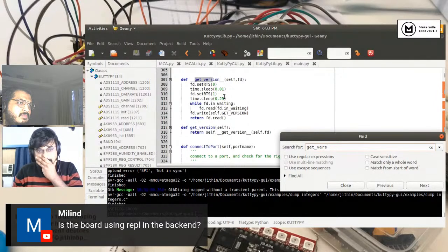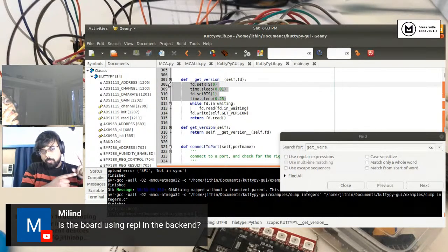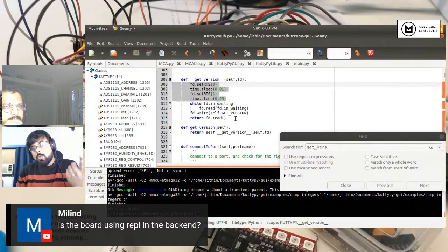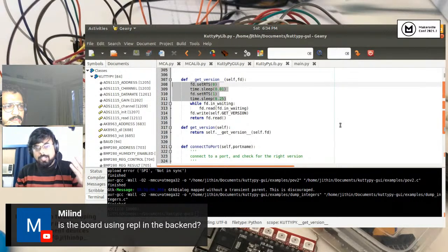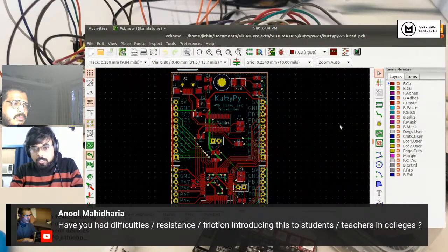So if you look at the code, let me just look at get version maybe. Yeah, so get version is just byte.pack 1. It's the number 1. So the get version function does two things. One is it resets the chip to make it go into bootloader mode. So the moment you call get version, if your code is running on the hardware, it'll stop execution and go back to the bootloader mode because the reset has been invoked. Now the bootloader will get command of it. You will send the get version command, and then you'll just read back a number, which is the version, and you see if it matches with the version that's meant for Atmega 32. I just have like three or four command sets and some specific ones for I2C communication so that reading from sensors is faster. And nothing more. The bootloader is still like 500 bytes something. It's pretty small.